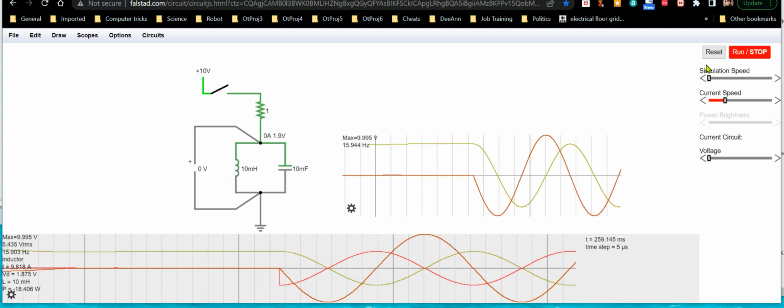So that's why I just left it here and hadn't been running it, so I could demonstrate this more clearly. Here the voltage waveform really stands out, so it's easier to see that this is the voltage waveform because it's so much bigger than the two current waveforms. You can readily see that the two current waveforms are 180 degrees out of phase with each other. But they're all relative to the phase of the voltage.